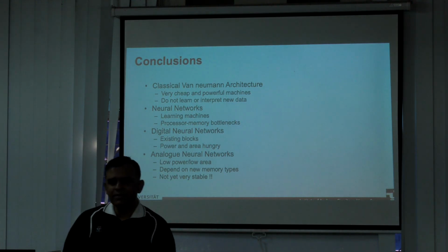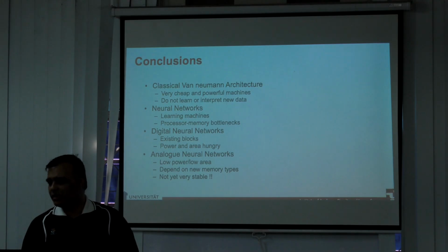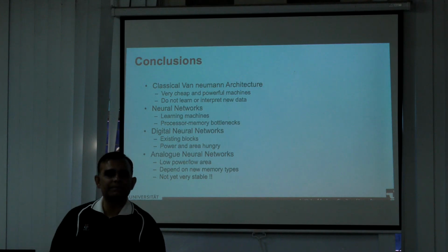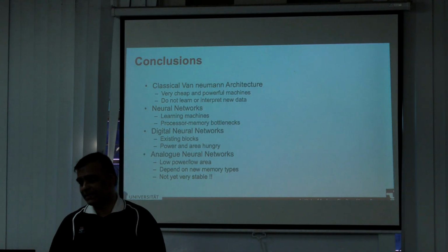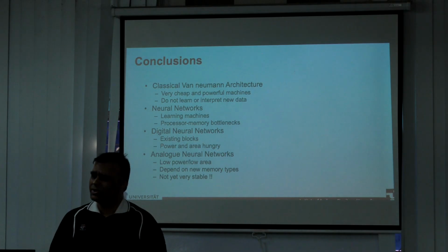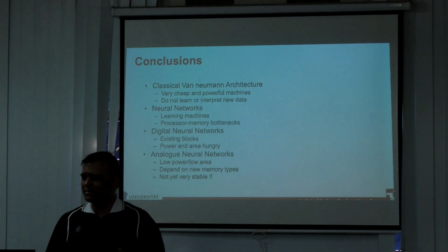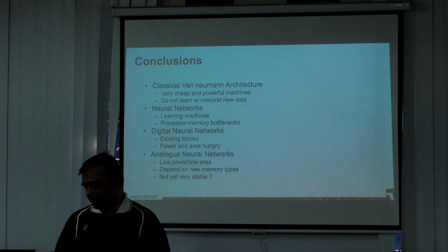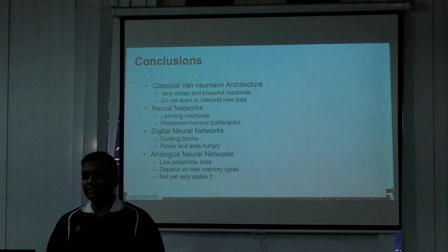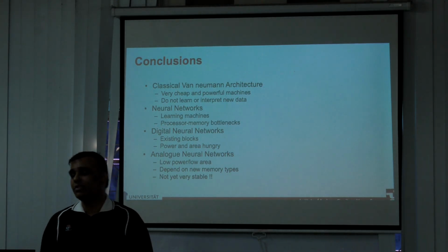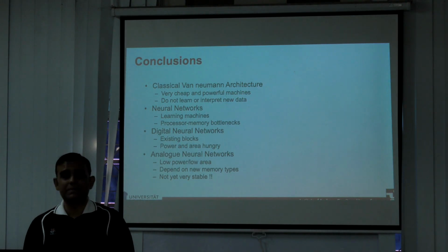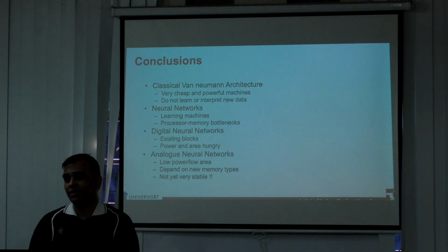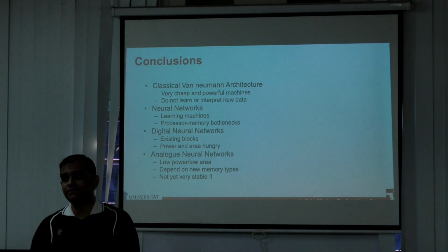We can make a neural network out of digital circuitry which is available to us. Analog seems to do a better job at this point of time, or at least looks to be doing a better job. It still has all the issues of noise, variability, reproducibility, and those are still very high research topics for us to play with. But it is promising that if you're going down the direction of machine learning or neural network based systems, we might have to revisit the entire digital design the way we do it, or else power is going to be a big concern.